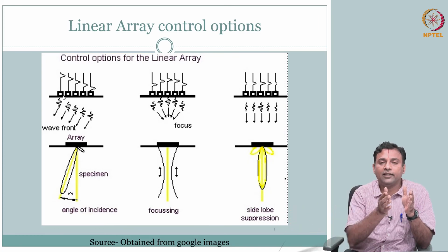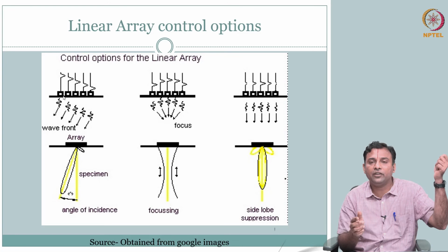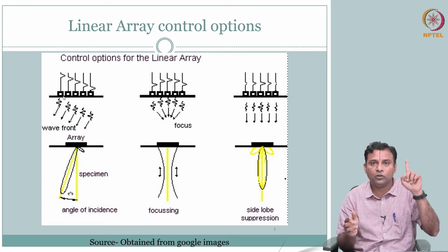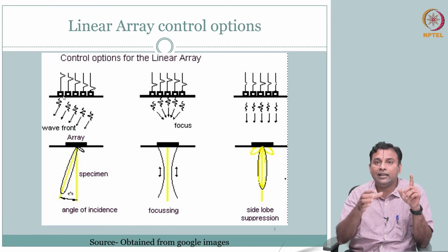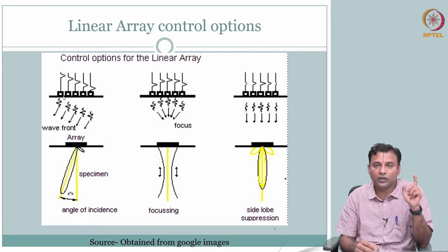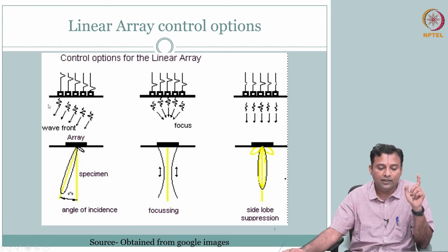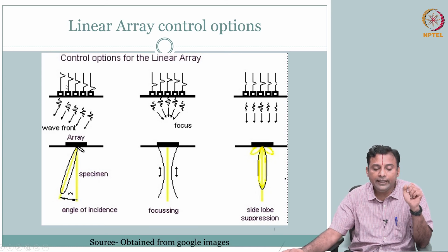When the sound comes back and hits, it vibrates, you get your electrical output. So, there was only one lead wire. If you look at the previous piezoelectric crystal single element that we covered, piezoelectric transducer. Whereas here what you have is multiple crystals, each one has its own control, each one acts as an independent channel. So you have electrodes for each of the crystals.